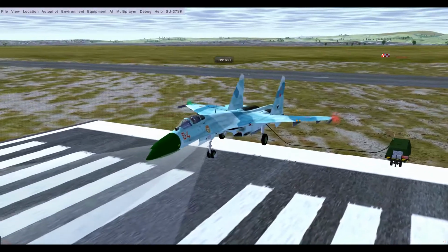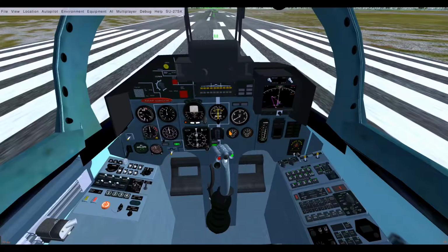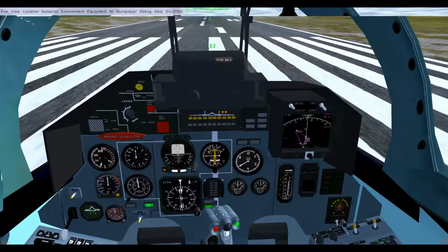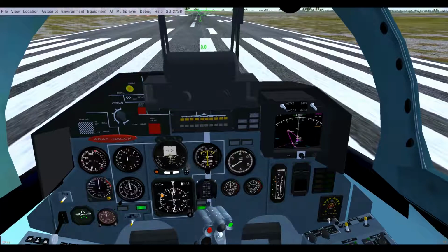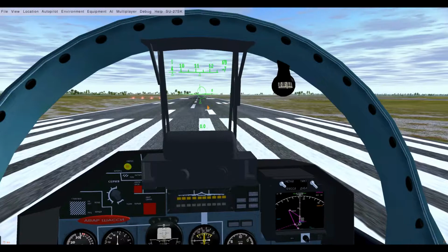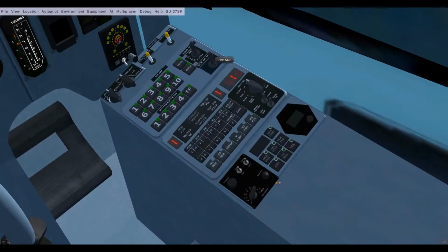The system monitors input from sensor devices and controls the indications in the instruments in the cockpit, such as the HSI, the horizontal situation indicator, and the head-up display, by the data provided from the onboard computer or the radio navigation systems, such as the RSBN or the ARC navigation systems. These are Russian systems of navigation.